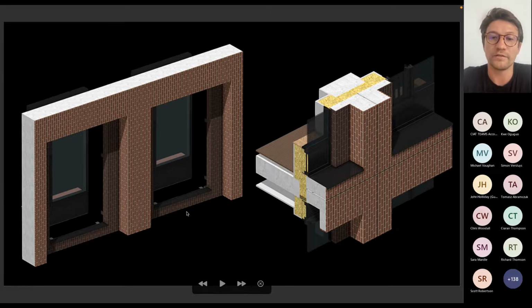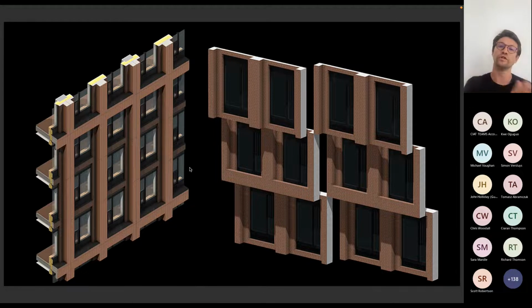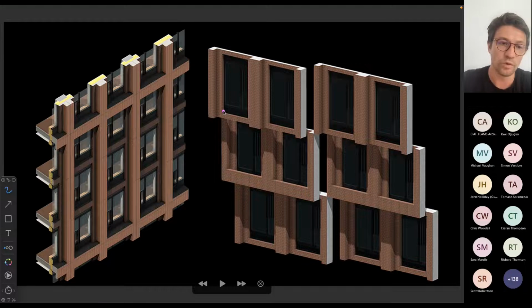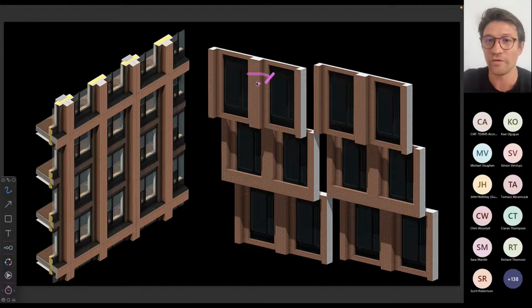Another thing to consider for these buildings is that it is also important to have a solid wall to vision wall ratio. A precast concrete contractor would want to have a certain amount of meat between the windows to get the structural integrity of these precast concrete panel donuts, because they are craned into position.